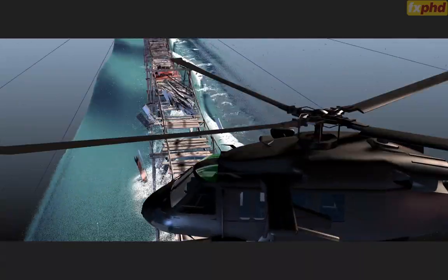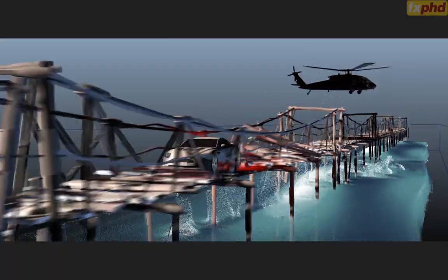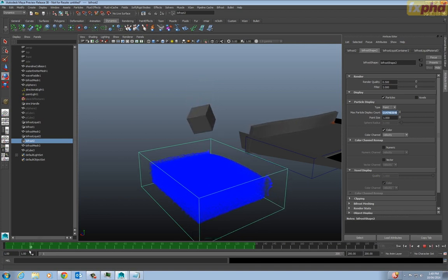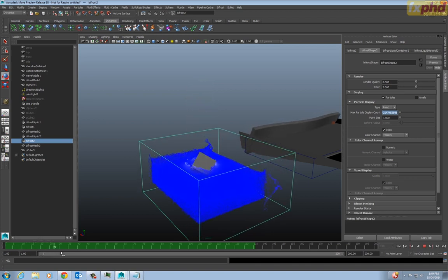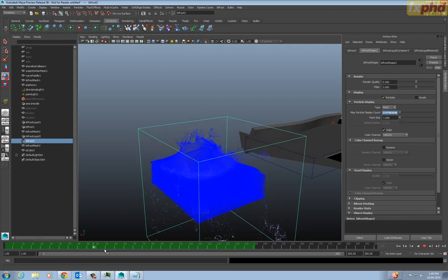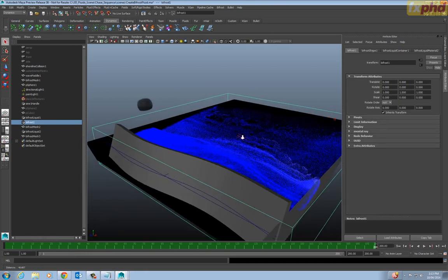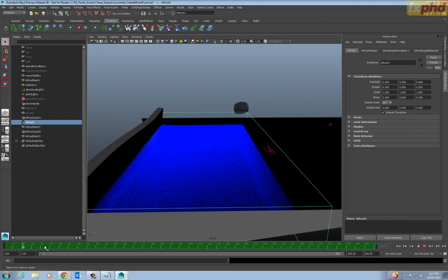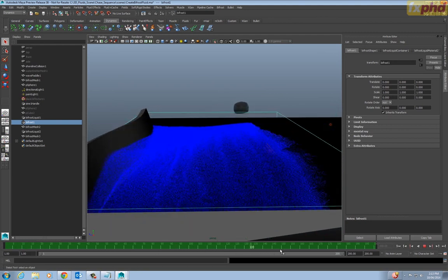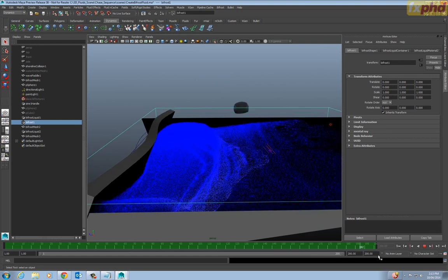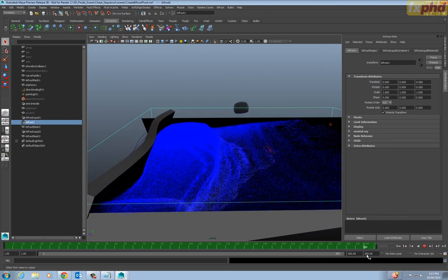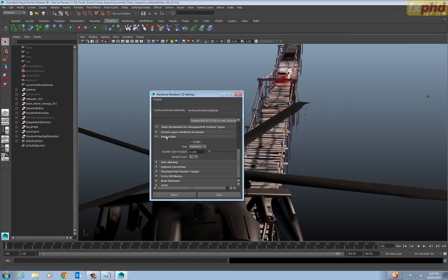We're going to get started though by just going over how to create a basic Bifrost liquid from scratch in Maya, and once we get into that, you'll be able to create simple collision geometry like containers and colliding objects. And we're just going to talk a little bit about the importance of the scale of the scene with Maya Bifrost settings, because the scale really sets the accuracy of the solver.